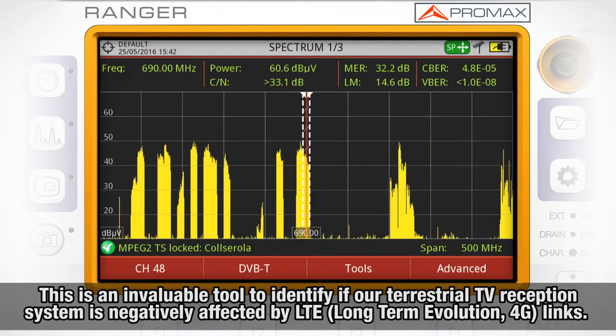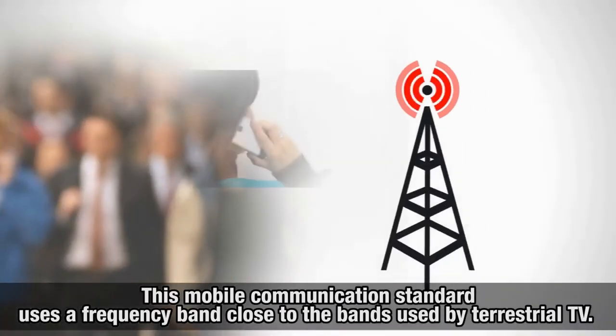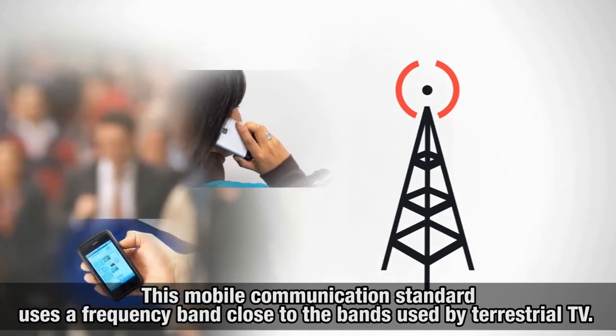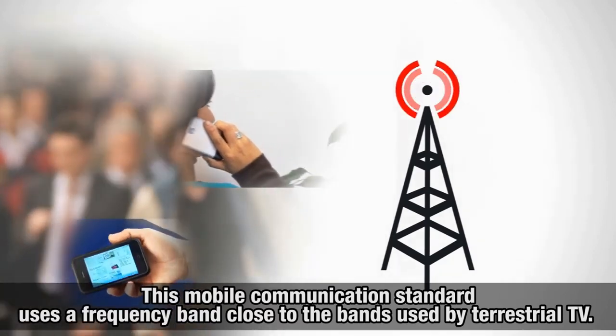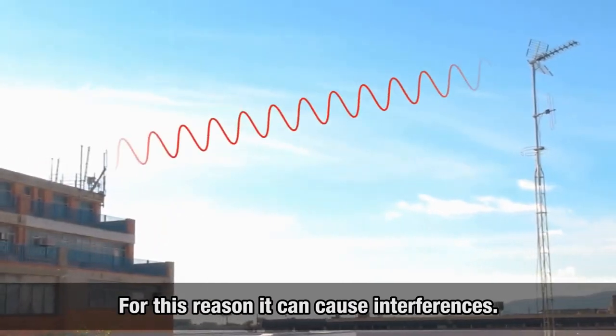This feature will be an invaluable tool in order to identify if our terrestrial TV reception system is being negatively affected by LTE links, long-term evolution. It is only available in case you are operating the meter in terrestrial band. This mobile communication standard uses a frequency band close to the bands used by terrestrial television. For this reason, it can cause interferences.